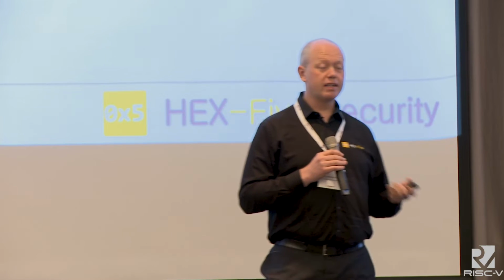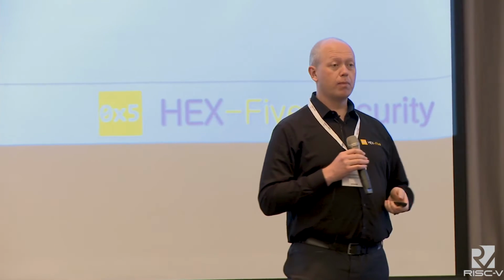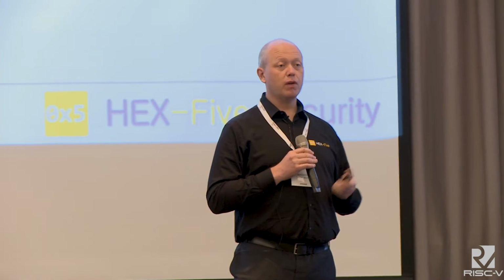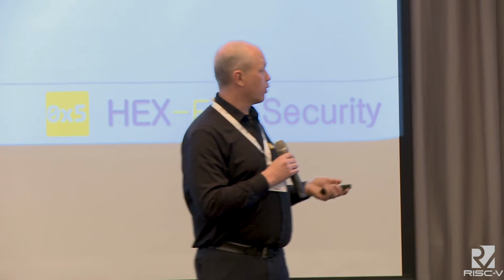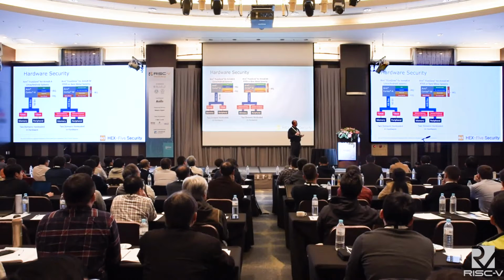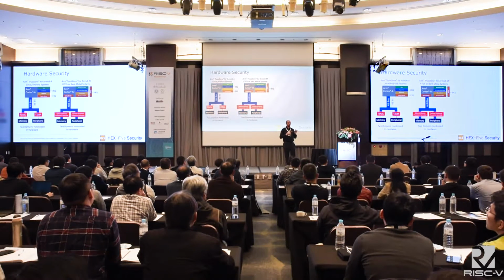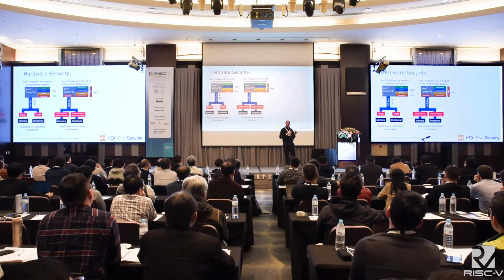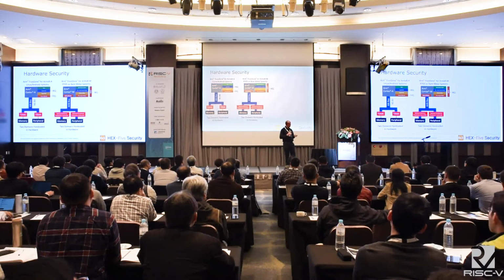And in particular, that's how you would filter for secondary bus masters. So if you have a DMA controller or something else that can also write into this bus, you need to have some other memory protection controller in order to filter that, because that's obviously outside of the core's purview. Problem here is we still have two domains that are hard-coded in hardware. We still very much have a secure and a non-secure domain, although we do have quite a bit more flexibility inside of them. This is, again, a much more modern architecture. This is about a 4 or 5-year-old architecture at this point.